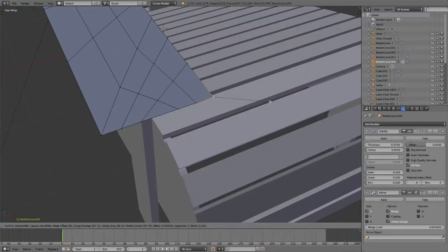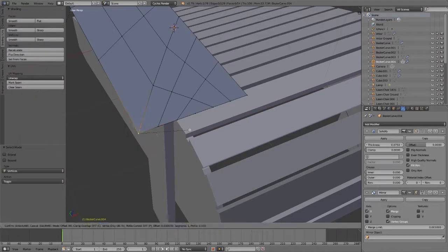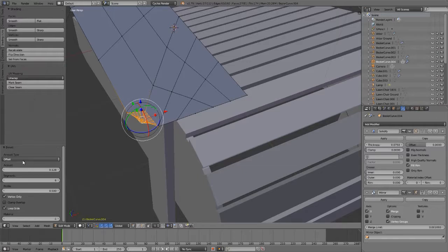That's no problem. This one's going to be a problem because it follows another line. So Shift Control B, it follows a third line. As soon as I roll the mouse wheel up, it recreates a corner because Blender's a little bit confused at the math of the geometry. There are other ways to handle the weight of a bevel. If we said this is what we wanted, we could change the bevel amount type. Depth, percent, offset, width. None of it is going to do us any good right now.